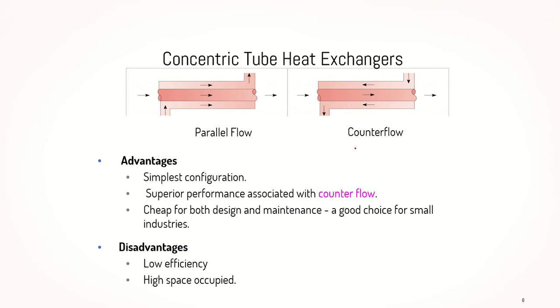But the disadvantage would be its low efficiency, and in order for us to have a higher efficiency, we would need a counterflow, but it's still not up to the standard of a shell and tube heat exchanger, and also the high space occupied.